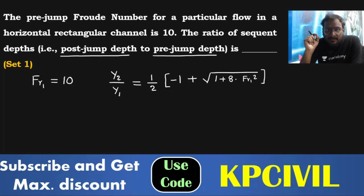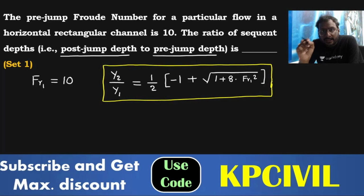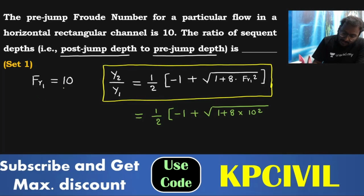I have repeated this several times in my classes. This is the most important equation, and we mostly expect questions from this formula. y2 by y1, post-jump by pre-jump, is equal to 1 by 2 into minus 1 plus under the root of 1 plus 8 into Fr1 square. The remaining is simple formula substitution only: half, minus 1 plus under the root of 1 plus 8 into 10 square. Fr1 is given, Fr1 is 10, just 10 square. So you calculate it.